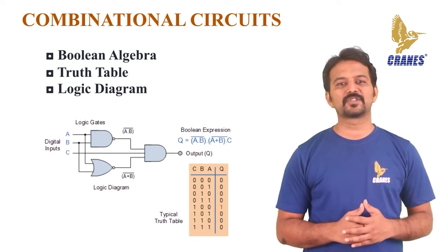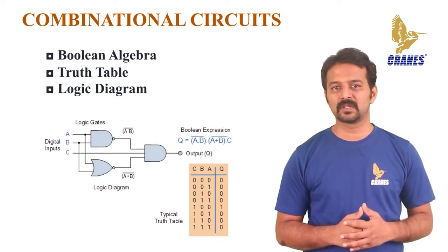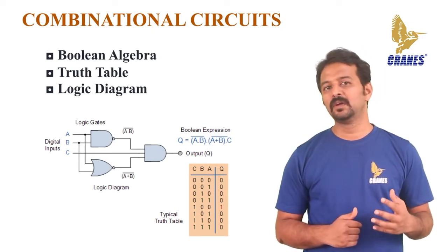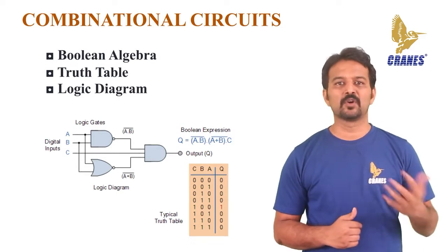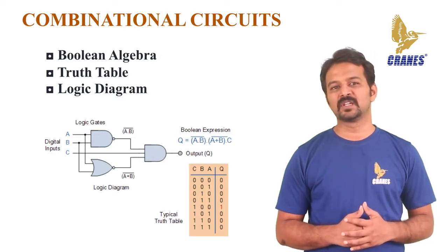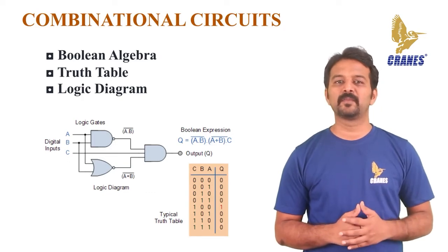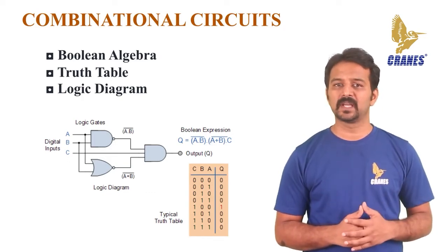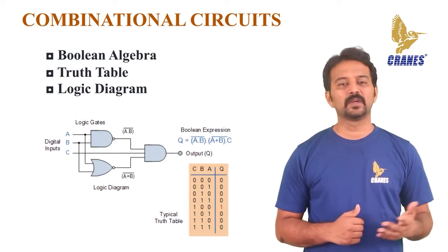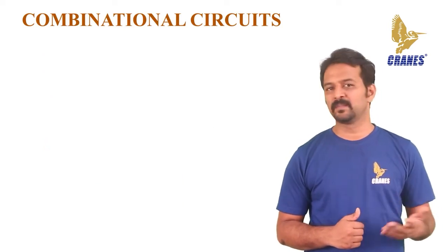As combinational logic circuits are made up of individual logic gates only, they can also be considered as decision-making circuits. Combinational logic is about combining logic gates together to process two or more signals in order to produce at least one output signal according to the logical function of each logic gate. Common combinational circuits made up of individual logic gates that carry out desired applications include multiplexers, demultiplexers, encoders, decoders, half adders, full adders, and many more.